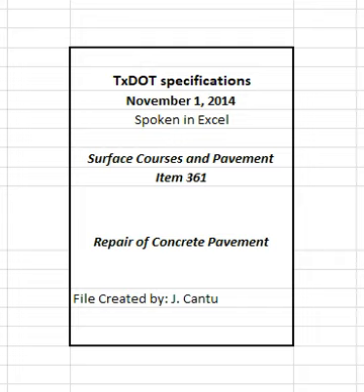The selection of repair material should be based on the time for opening to traffic and temperature range during the repair. Provide Class E concrete in accordance with Item 421, hydraulic cement concrete, and designed to attain a minimum average flexural strength of 255 psi or a minimum average compressive strength of 1800 psi within the time frame designated for opening to traffic if it is less than 72 HR after concrete placement.